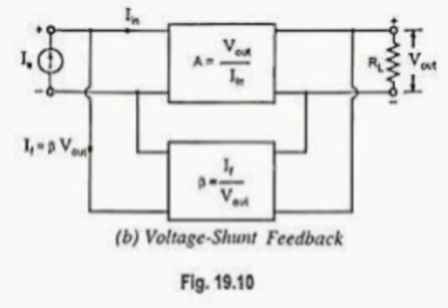Bias currents and voltage. V0 not equal to 0 is called output offset. Balanced condition: IB1, IB2. For the two inputs, one voltage source is connected to plus, one power source to minus, and the same is grounded. That is called balanced condition. Input bias current IB equals (IB1 plus IB2) by 2. Input offset current IIO equals IB1 minus IB2. Input offset voltage is the voltage which must be applied between the input terminals to balance the amplifier, that means V0 equals 0.